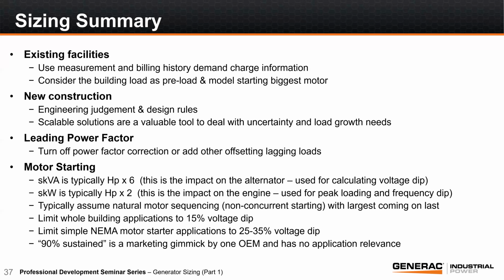Just like anything else, the enemy of the long-term care of a piece of equipment is how hot it gets. The more load you put on it, the hotter it's going to get. So if you're applying a generator in a peak shaving application versus a standby, you may be a bit more conservative in the sizing of the generator, simply because you're going to be putting more hours on the piece of equipment. So your average load factor, instead of being 75, maybe 80%, we're going to put an average load factor of somewhere around 70%. Great.